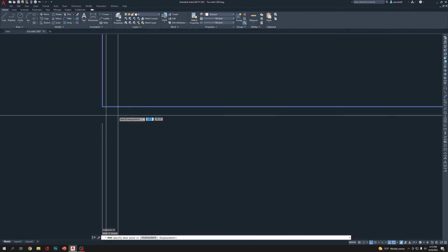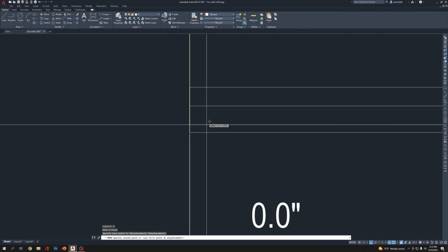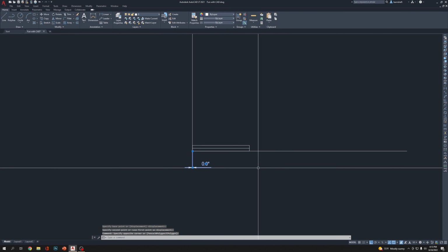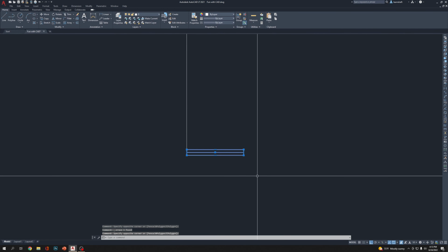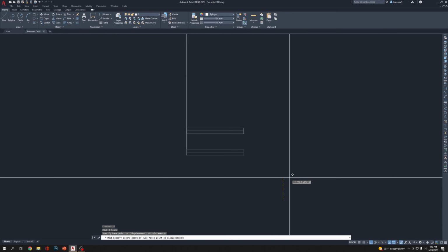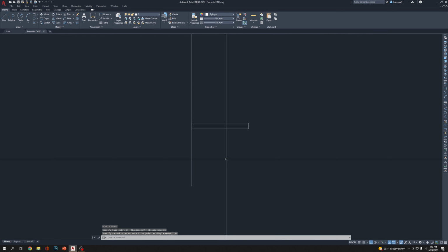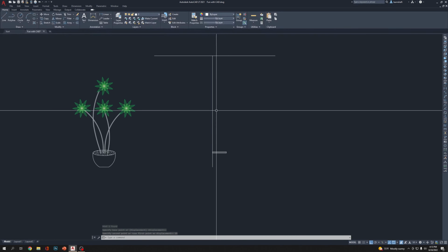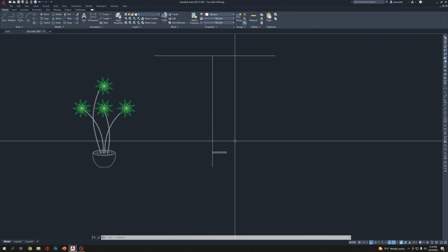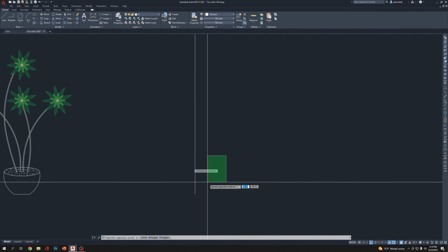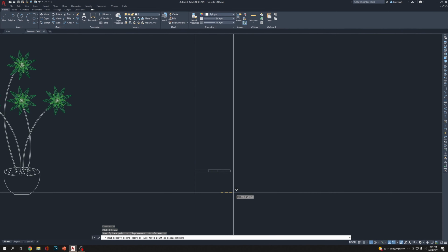So I'm just going to select this corner, take it to this corner, delete the line, you can delete this line too, select now this one, move it just 15, enter. And wait, the corner thing is going to be a piece of wood, which is going to be a little strong wood, so we should keep space for it. So I'm going to select this one, moving it 3 inches out.